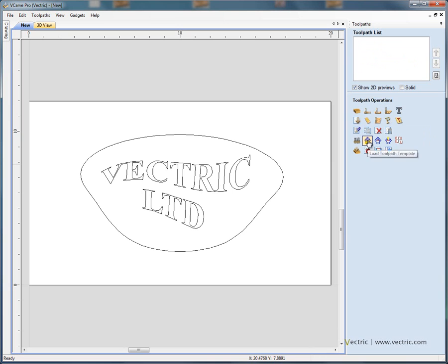So click OK. Here we've got the toolpath operations, and the first line of toolpaths are what we refer to as the 2D toolpaths, so creating simple profile toolpaths, pocketing, drilling and quick engrave toolpaths. The second row are the 2.5D toolpaths, so V-carving, fluting toolpaths, the texturing toolpath, raised prism toolpaths and the inlay toolpaths. If you're working with a spire, there will be another row of toolpaths in here for 3D toolpaths.